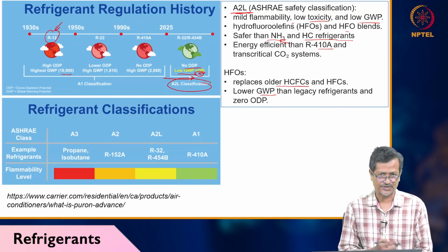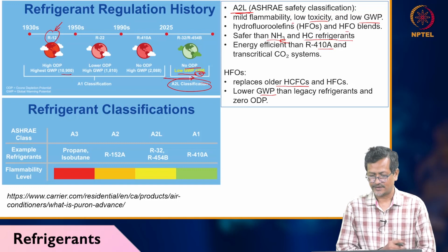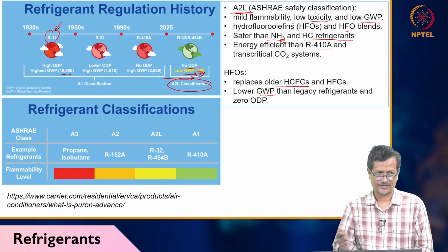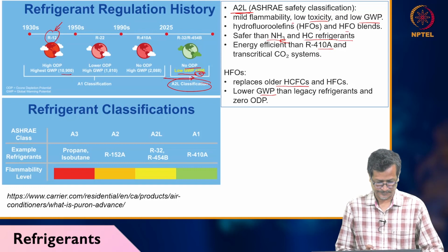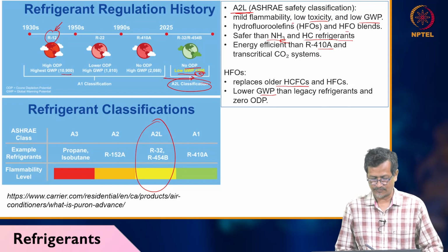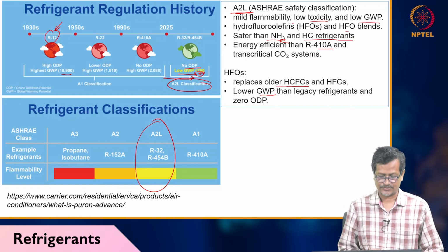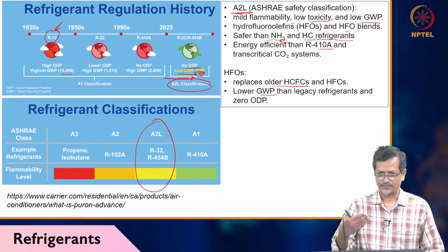They are making systems more energy efficient and less noisy, working on the pump side and on the refrigerant, developing new mixed or single compounds and new series of air conditioners or refrigerators. For A2L, the examples given are R32 and R454B, and there will be many others. Many companies have their own names and put in some extra chemical to improve certain properties.